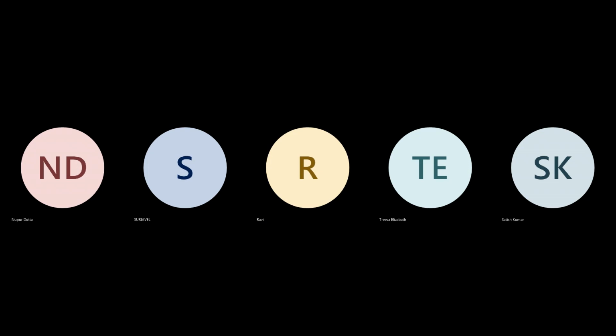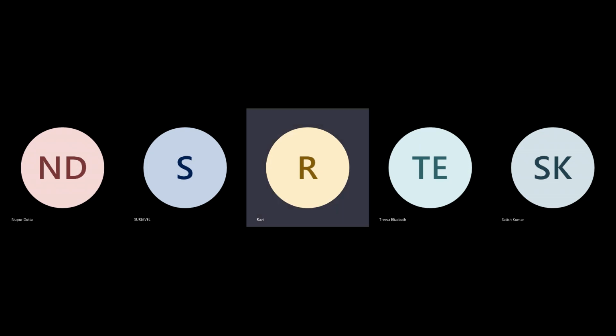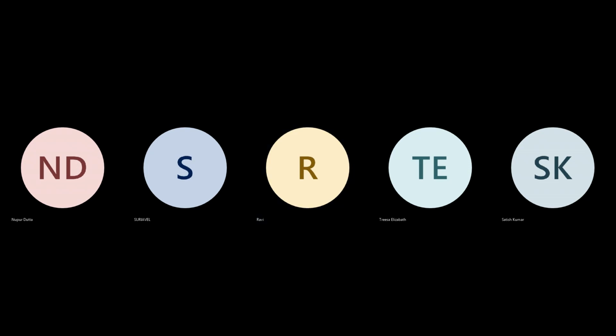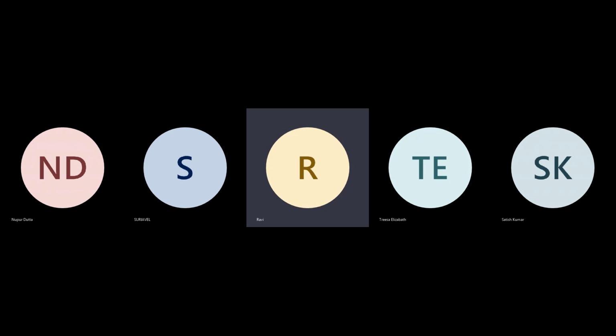Actually, you see, there are two aspects to the delay of a cell in CMOS. One is called the diffusion impact. The second one is basically the mobility, the current flow mobility of electrons. As the temperature increases, due to the hot electron effect, the path from source to drain is a resistor path. As temperature increases, the resistance increases, and there will be delay.